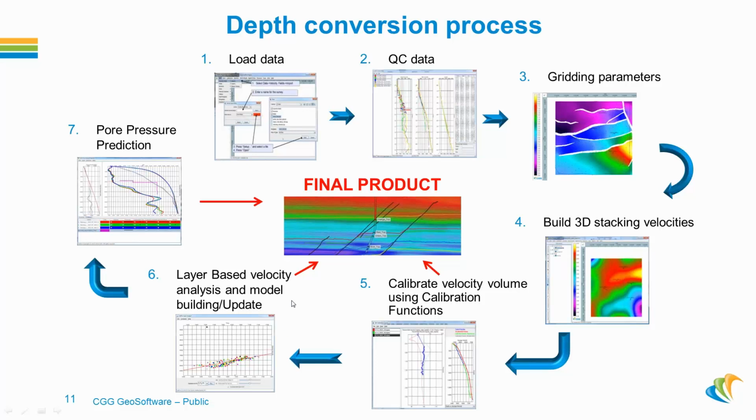After that, we can then go ahead and do the layer analysis. With this one, we have the opportunity to specify on each layer our velocity model with different tops and base, specify different events, apply different equations for each of the different layers that we have. And another important thing here, in this layer analysis, we can apply different techniques for every layer, and we are using the information, mainly the velocities. We can do that also with the check shot.